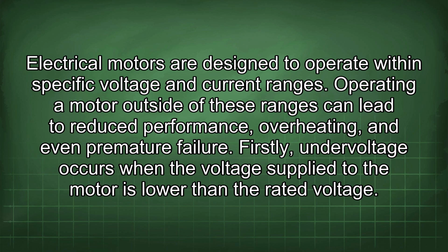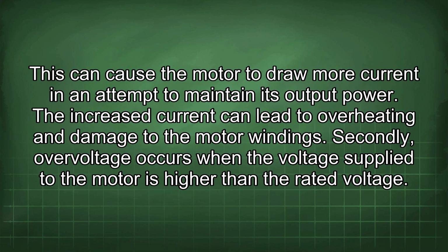Firstly, undervoltage occurs when the voltage supplied to the motor is lower than the rated voltage. This can cause the motor to draw more current in an attempt to maintain its output power. The increased current can lead to overheating and damage to the motor windings.